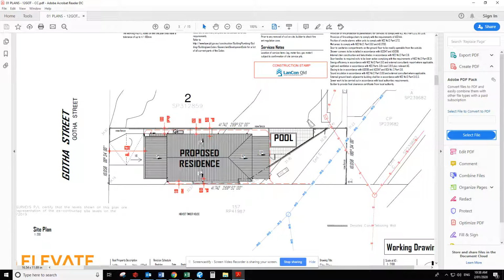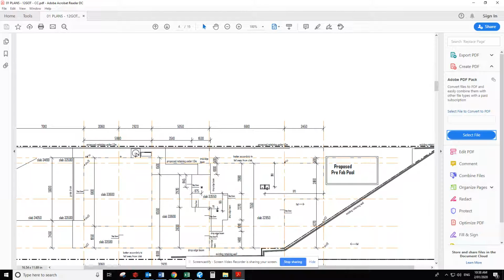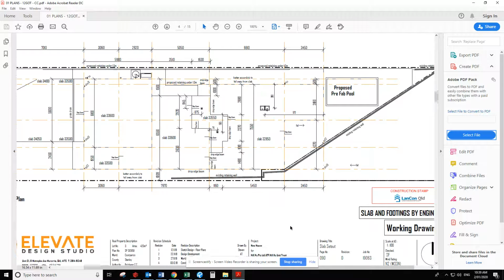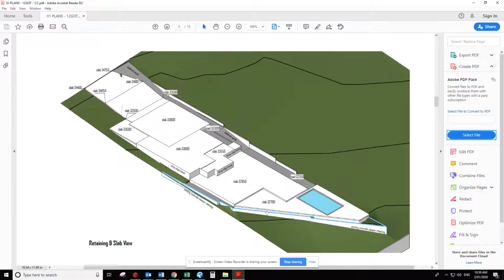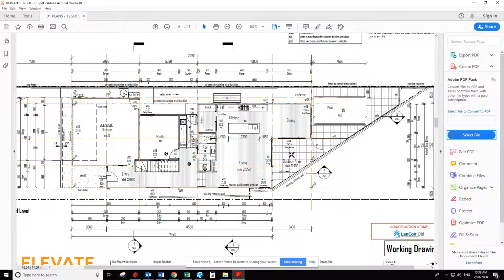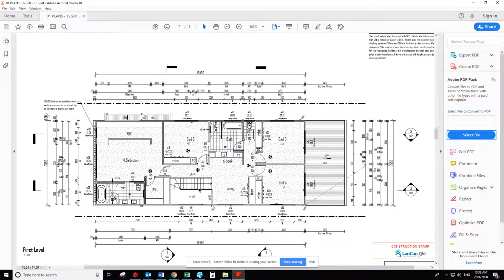And that shows that we need to put things like silt fencing along here. We need retaining walls. We need the drop edge through the block, as you can see from the other set of plans. So we get a lot of information from the levels that are provided to us by the surveyor. It depends on the particular job what's being provided by the time the sales estimator starts working on it, but all this information should be through before we actually start on site.